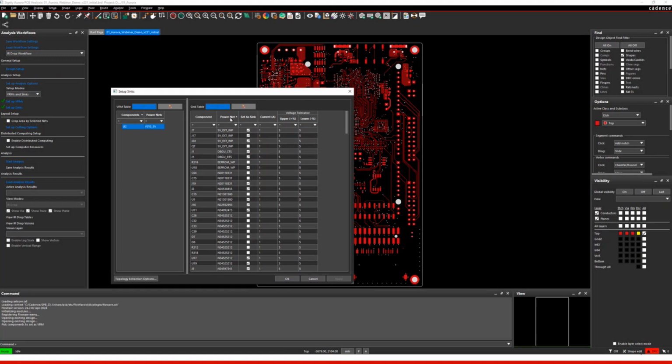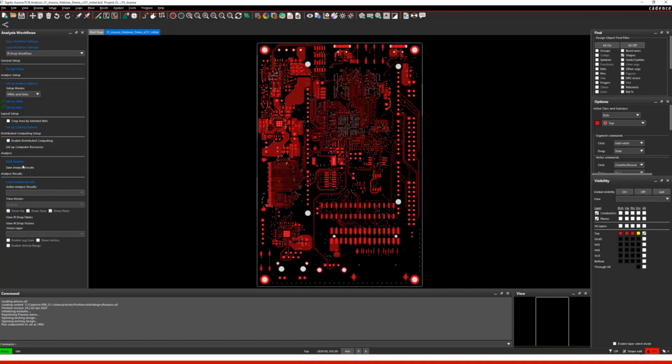We can also select here the correct voltage, and we also said, okay, we want to see the VCC 5 volts, and here, okay, capacitors do not make sense, but we want to see if we assign current to my D1 and also to a connector, let's say with a typical value of 1 ampere, but of course you can assign here any value that is realistic.